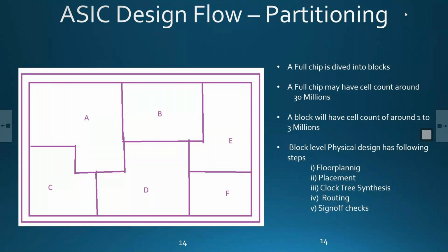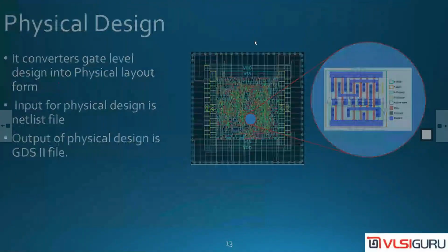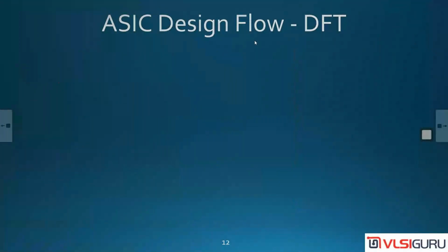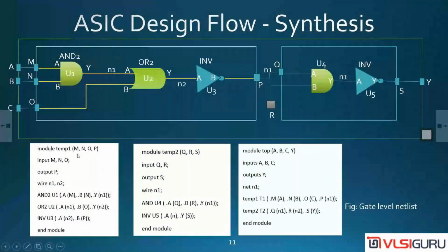So now it is module-wise division. Module-wise means estimate what is the area required for this entire complete module. So I cannot divide this full chip into different halves, right? What is the complete area required for this complete module? You can see this first module is having how many cells? 3 cells. Second module is having only 2 cells. So the second module requires less area. First module requires more area. Like for each module, how much area is required? Based on that, you divide the chip.